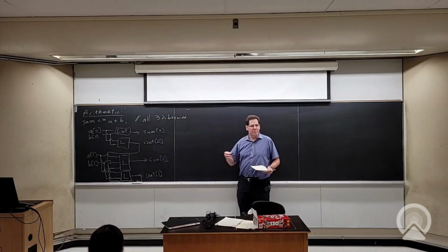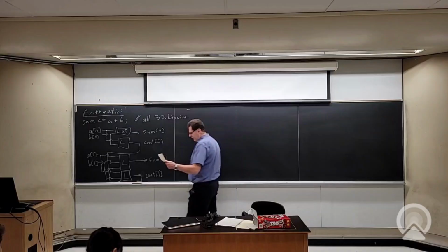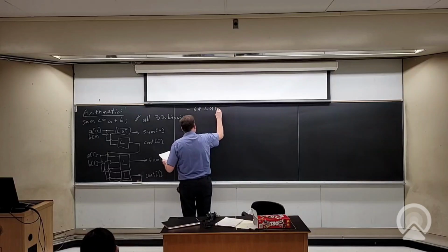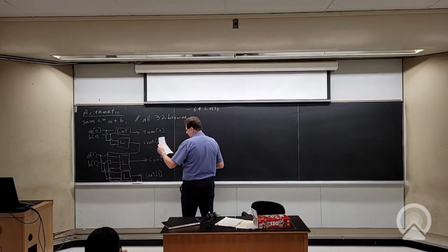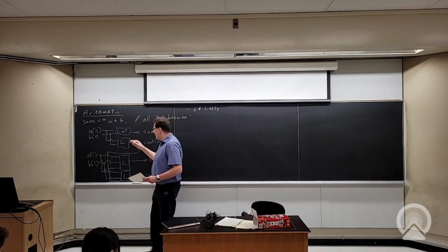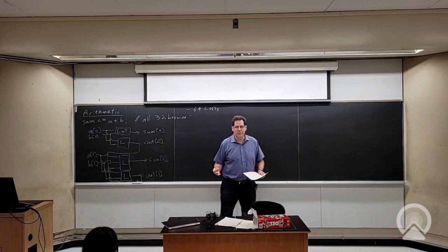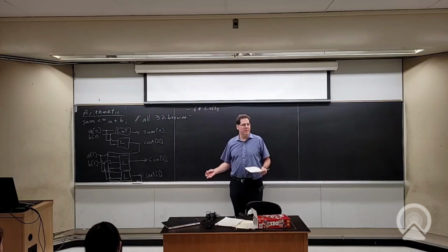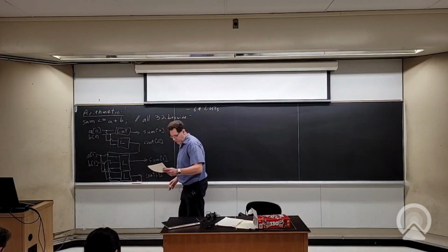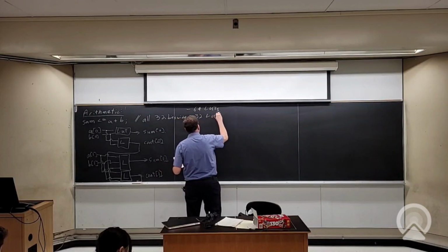So how many lookup tables do I need for this 32-bit adder? Right, so I need 64 LUTs. Okay, so the depth of a circuit is like the number of things in series on the critical path. So for this adder, how many LUTs do I have in series? Yeah, so I have 32 LUTs in series, right? All the way through the whole carry chain. So those 32 LUTs will be my critical path.